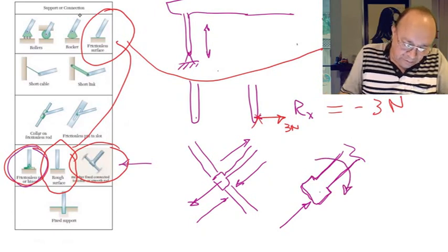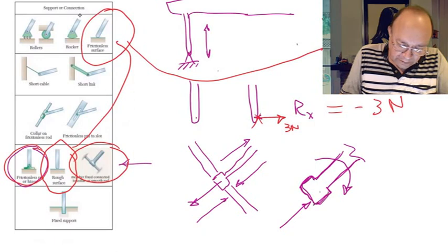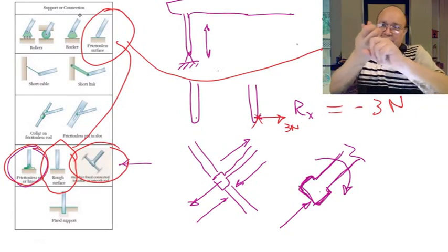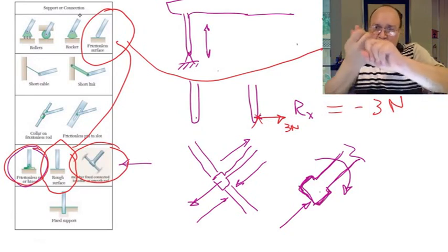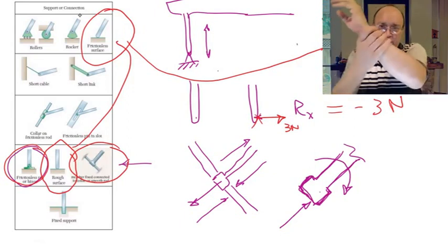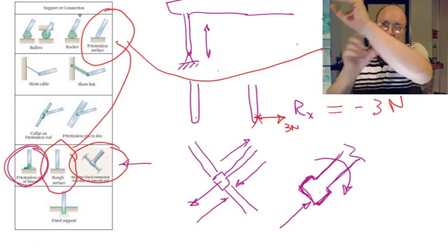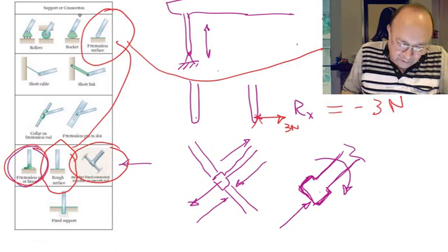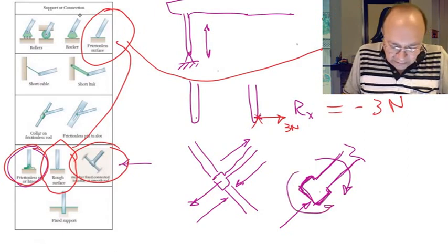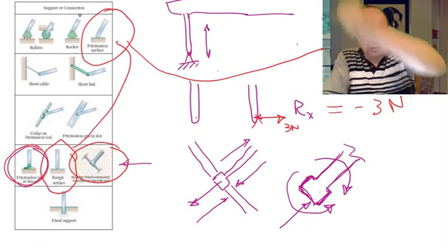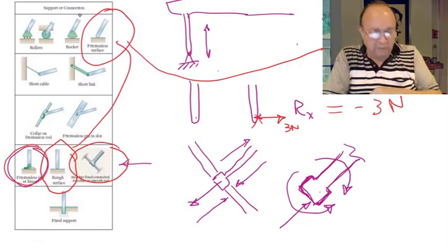Well, because of the construction of this collar, it's rigidly connected like this. It doesn't allow for rotation. The rod is fixed and the collar has dimensions big enough to not allow for rotation. So the rod is going to apply a moment that is opposite to any rotation that the body is going to exert over the rod.